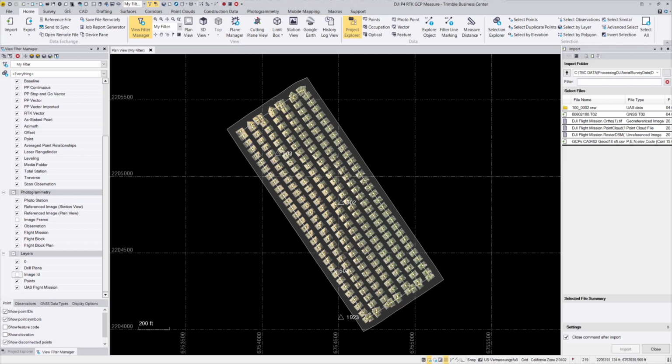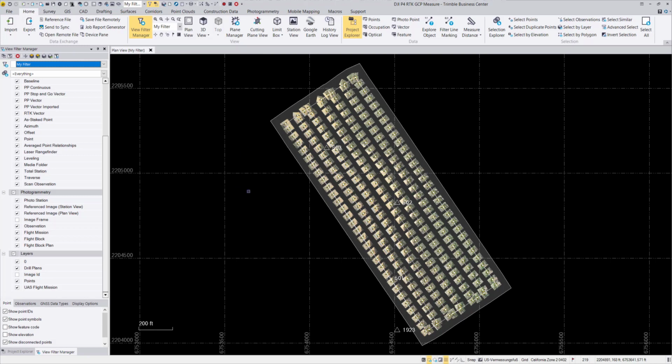I would love to have them in the 4 corners and one in the middle, but it doesn't matter. We have GNSS, so we will measure only the control point 502 now, and together with this measurement of 502 and with the GNSS, run the adjustment again afterwards with ground control points.